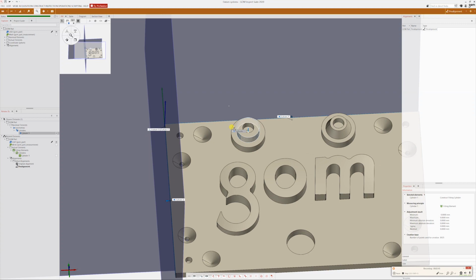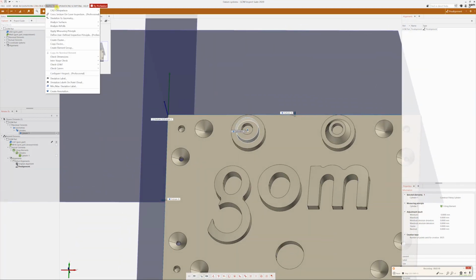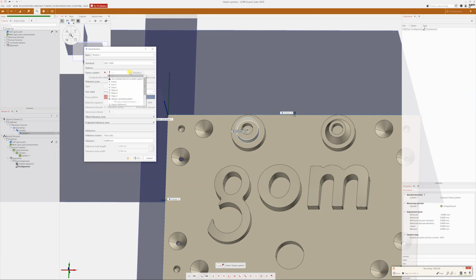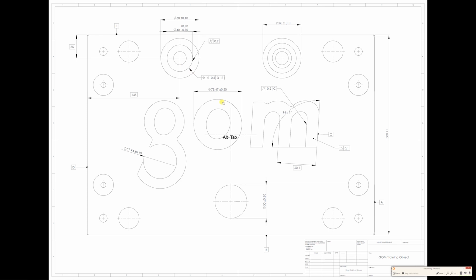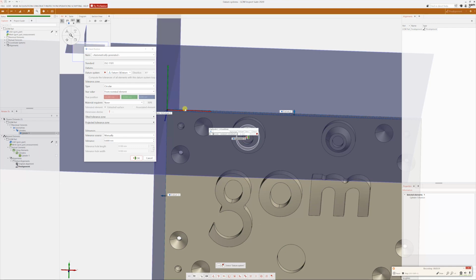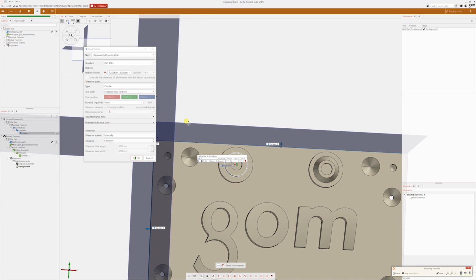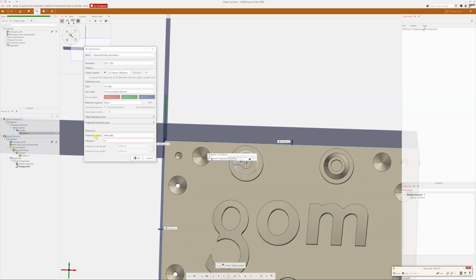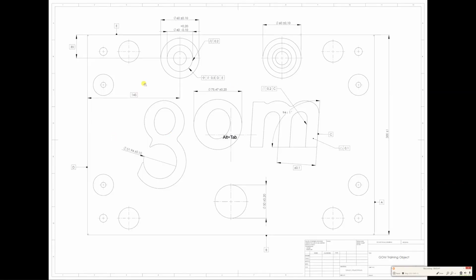Okay, good. And now let's evaluate the GD&T position. Datum system D and E. I think it's a circular. Yes, it's a circular, and it has to have 35 on this direction and 145 on this direction. Okay, so as we see here, 145 on the x-axis and 35 on the y-axis. So we can see this is the x-axis and this is the y-axis. Okay, and we have 0.5, right? 0.5, yeah.